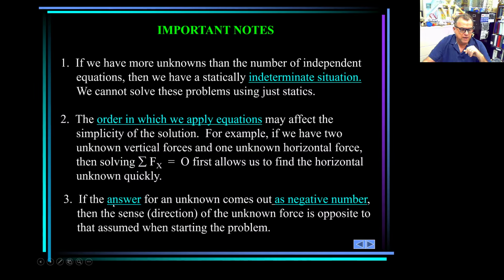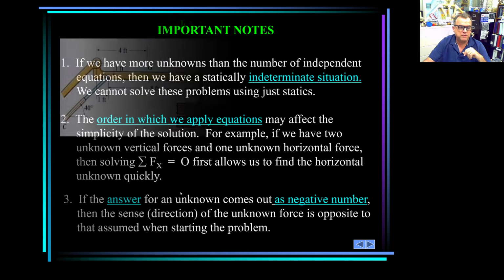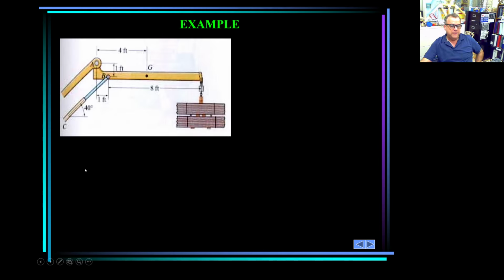What else? If the answer for an unknown force, whatever, or moment comes negative, that means that the sense or direction was opposite of whatever we assume. I'm going to explain that with this example.